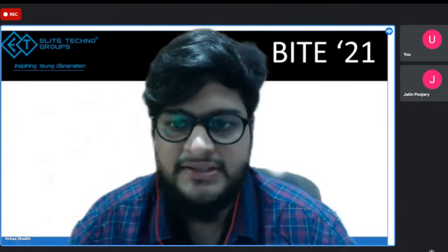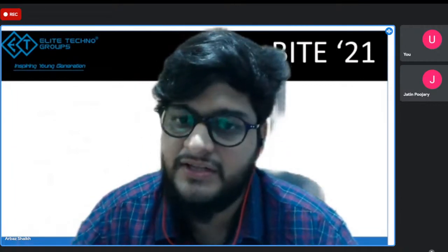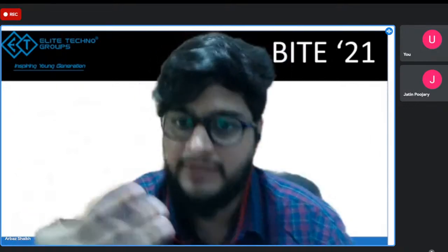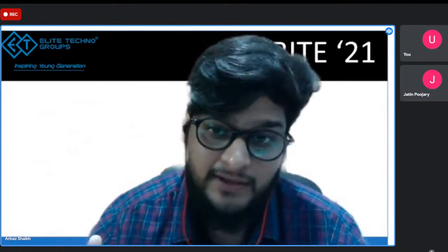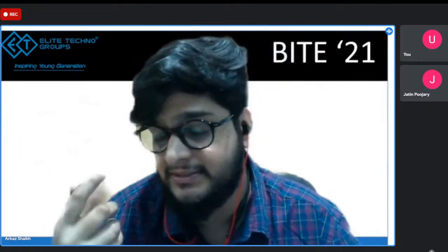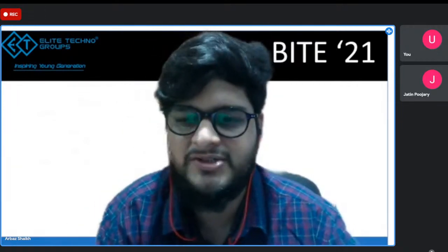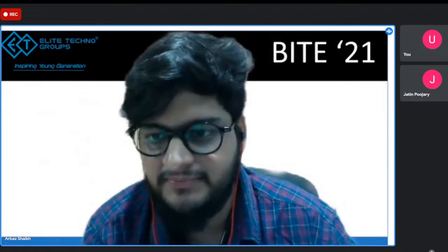Adarsh is asking which device is used to measure the slip angle. It's not a device, it's an experimental process where you apply some amount of load and turn the wheel, and see how much it is turning and in which direction the tire is deformed. With that, you can calculate the slip angle. There's no particular device that I know of, but I just know of the method.